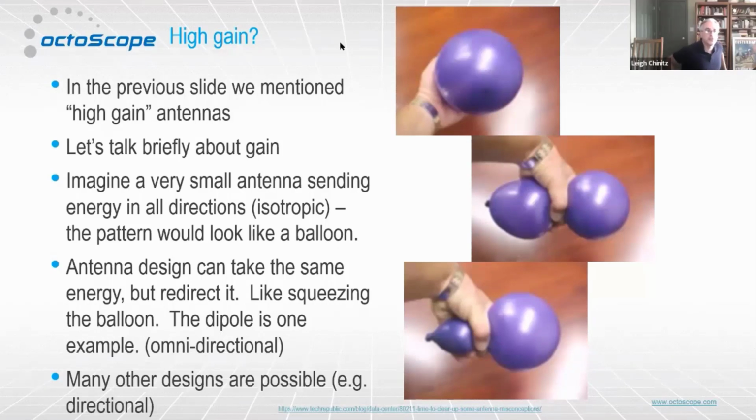Well, return loss is a characteristic of the antenna, right? You can't optimize it. What you can do is choose the right antenna for the test that you're doing. So, for example, part of the reason we have such a wide bandwidth antenna in our test bed is that we want people to be able to do tests throughout the frequency range that the test bed supports.